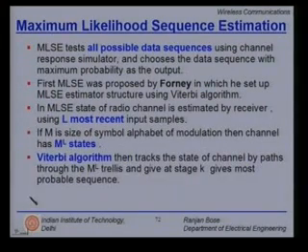The Viterbi algorithm then tracks the state of the channel by paths through the m raised to L trellis and gives at stage k the most probable sequence. So, it is some kind of sequence estimation. Needless to say, it will be computationally very intensive, but you will get a much better minimum mean squared error.